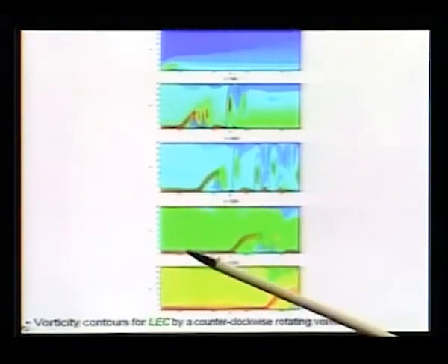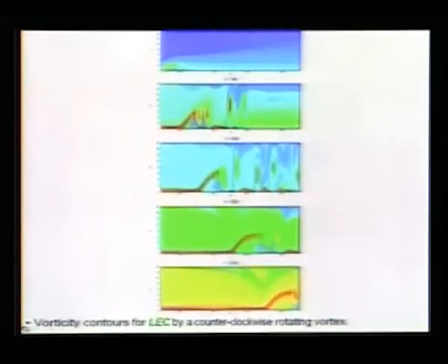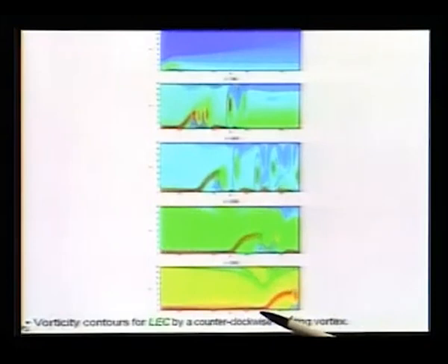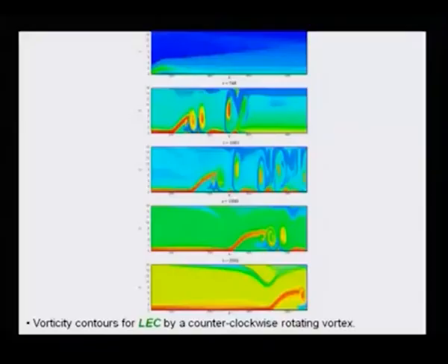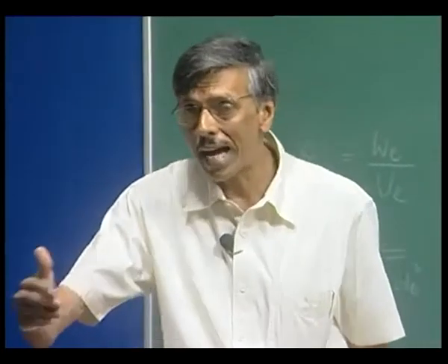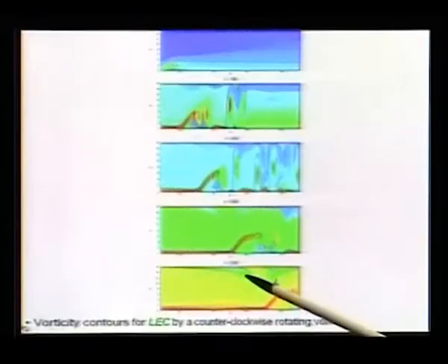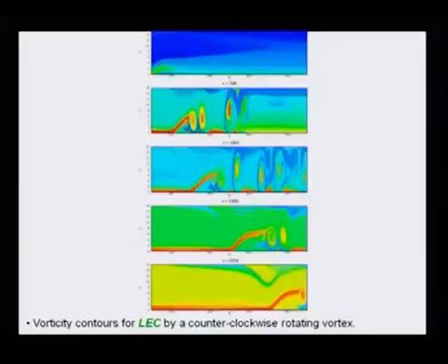And in the rest of the place where its effect is marginal, you can very clearly see that it is almost like a constant thickness boundary layer. And here you are also seeing the same thing, but now here it has created a significant thinning down, because it has acted over a longer period. See, this is about 1500, this is 2000. So, over a longer period, the same favorable pressure gradient has acted upon.